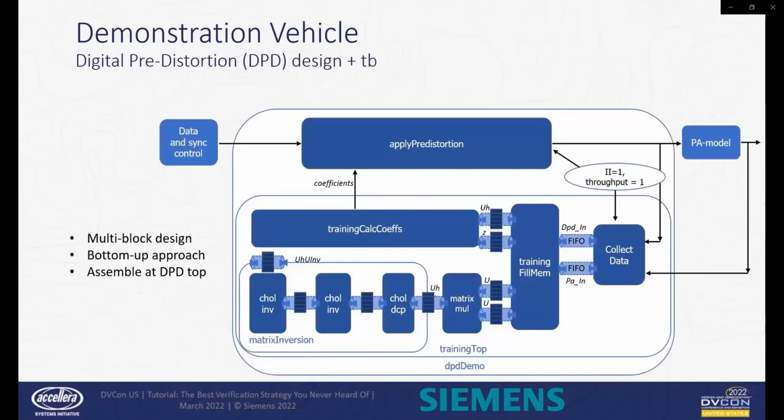One additional slide providing yet more detail on the design and the test bench, again both at the C++ level of abstraction. We will break the design into a handful of building blocks, each which will be synthesized standalone via HLS. Then, still via HLS, the blocks will be assembled into our design top. This approach is what's referred to as a bottom-up approach, with assembly of the DUT done from lower-level building blocks.